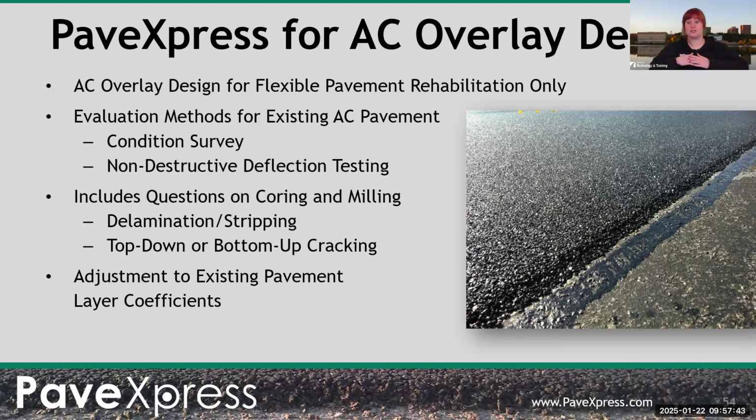If the program is giving you some crazy thick layers, then maybe now you start, like Chuck said, thinking about optimizing and changing some things. Maybe you go with a stabilized subgrade or stabilized base, something that's going to give you a little bit more structure rather than having 3 feet of sand. Then maybe you're just putting in a lot of extra and raising the grade of your road. There are a lot of other considerations to take into account too.